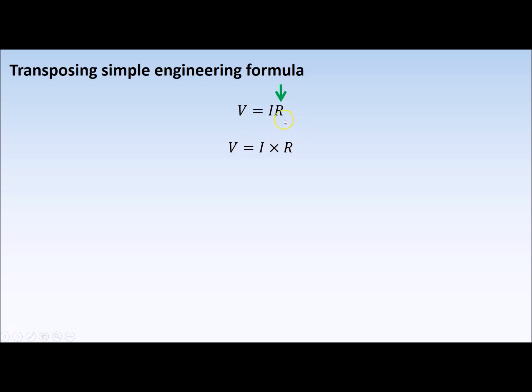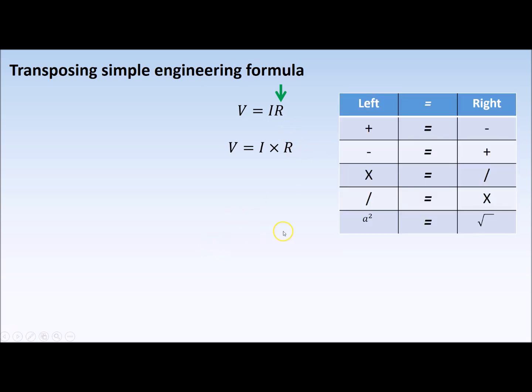Now in the next example, we know the voltage, and we know how much current is being drawn in the circuit, so we want to work out the resistance of a particular circuit. Going back to our chart, these two are times together, so we've got a times here. What's effectively going to happen is we're going to use it as a divide by. We want to get R on its own, so we need to move I. The next step is to divide by I.